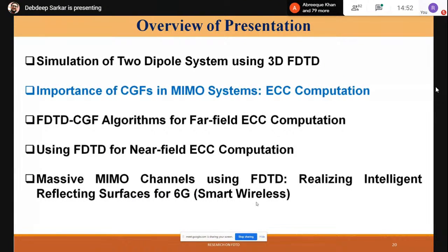Well, with that background, I come to the last leg of my lecture. I will discuss how a simple code like the 3D-FDTD code can assist you in your own research. One key area where I made use of this FDTD routine, this conditionally stable, Cartesian coordinate based, very primitive kind of FDTD routine, was in solving some very important problems relevant to the MIMO antenna community.